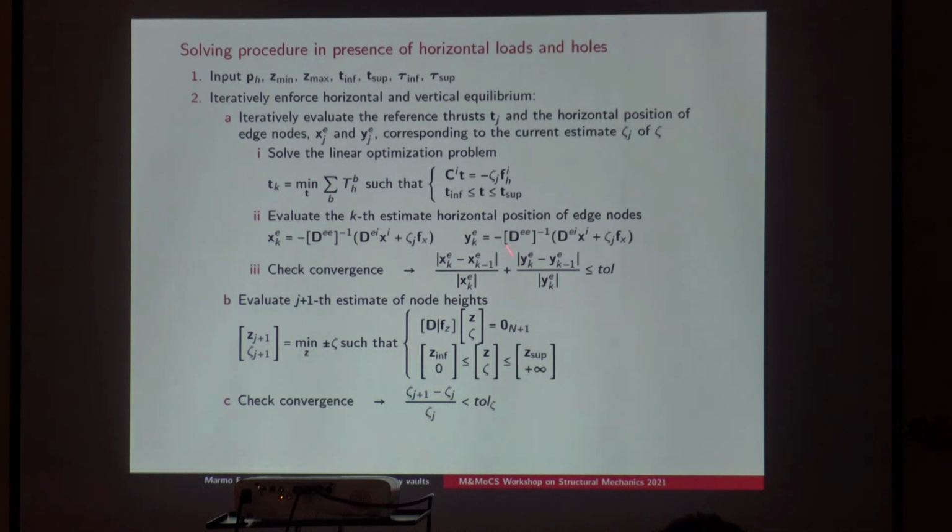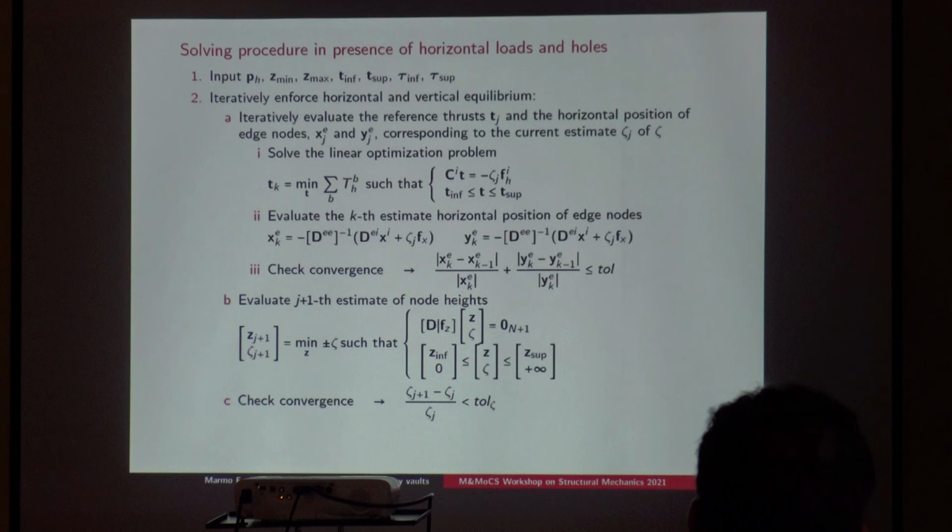First, to define the limit value for the thrust. So if we want some part of the structure to work under some stress distribution, we can control that by assigning these limits for the thrust values. But we have membrane limit values, and so we can use that equivalence to find the thrust corresponding to that membrane limits.